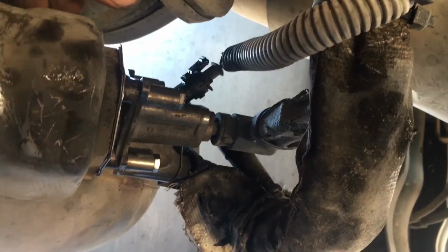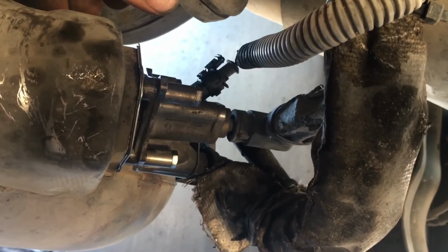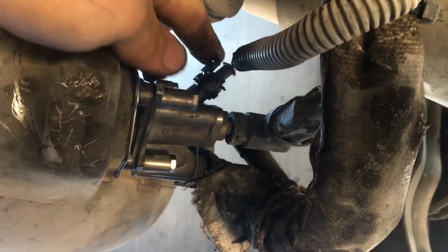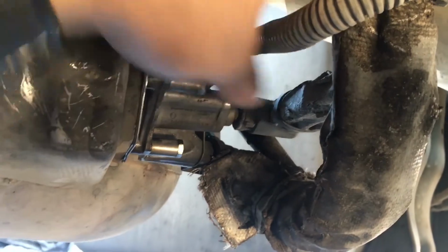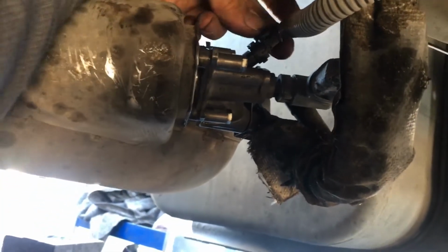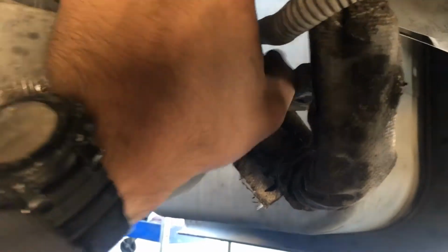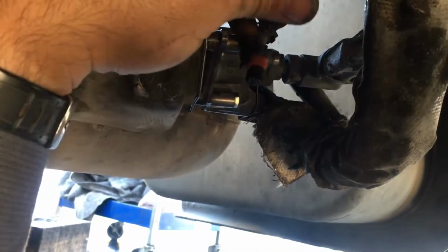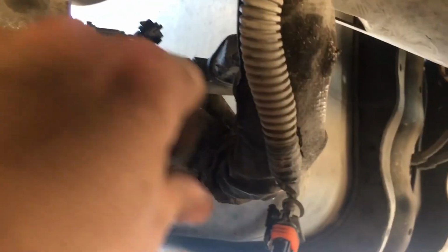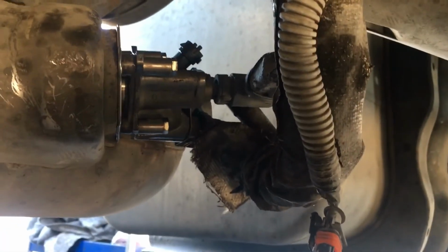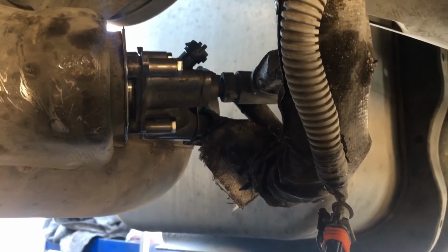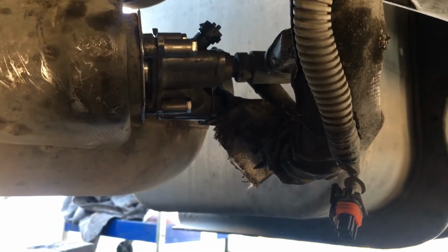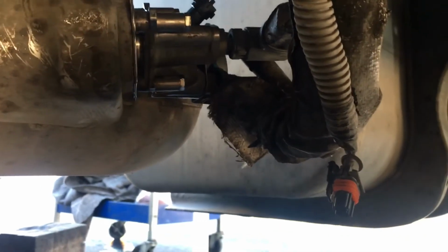Before we run the regen, we have to climb back underneath to our doser and unplug the electrical harness. Just push down on your clip and pull up, and push it out of the way, away from the hot pipes, because this is going to get really hot in a second. You're going to have some new fault codes in the computer and in the dash. Don't worry about it, it should still run a regen, but we need this unplugged in order to get the correct reading on our sensors.